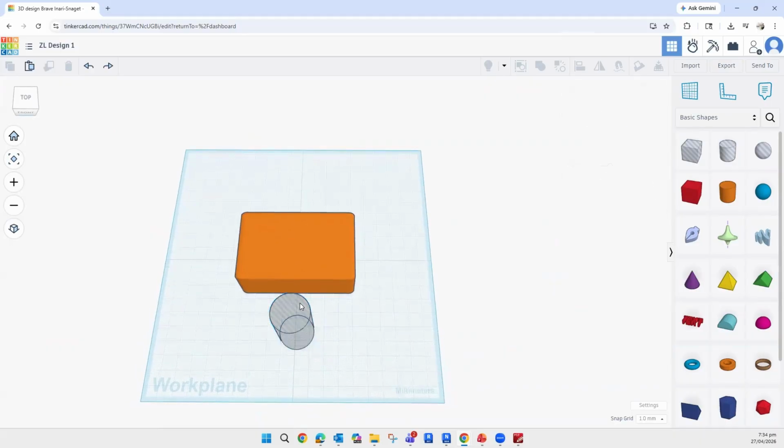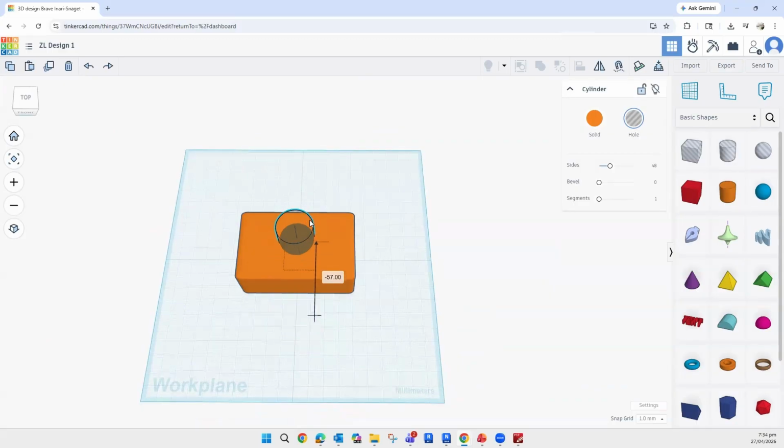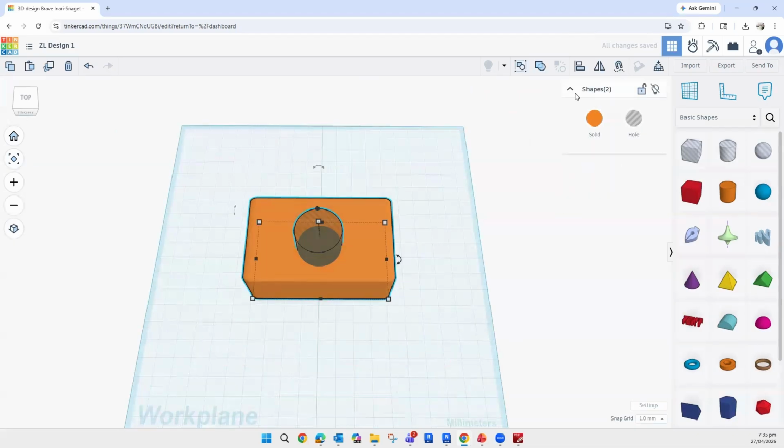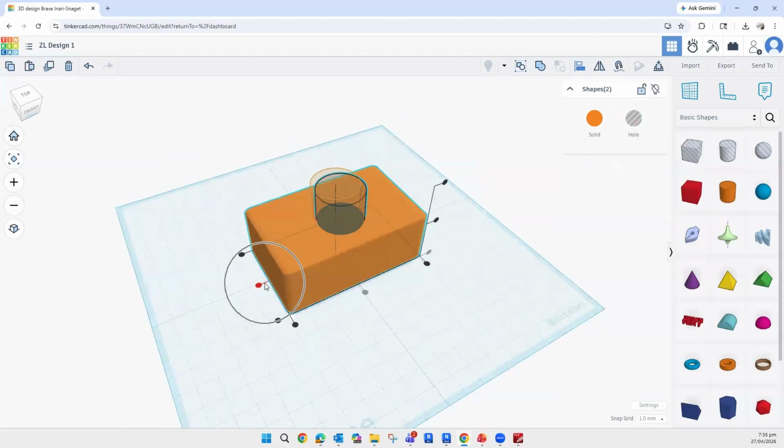So what we can do is, once we have completely aligned to this vertical side, right? We select this cylinder. We press the shift key and drag the mouse and hold it there. So that works this way. After you have moved it into this element, then stop. Select it again, go to align. Then now you can select this center line. Yeah, so if you select this center line, that's cool. That's already in the center.